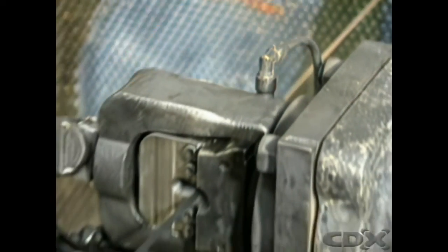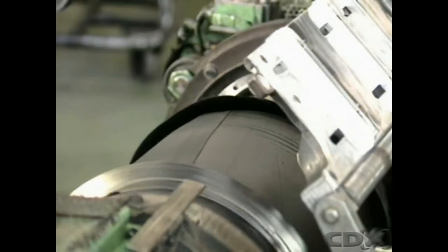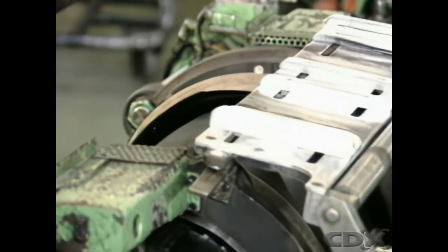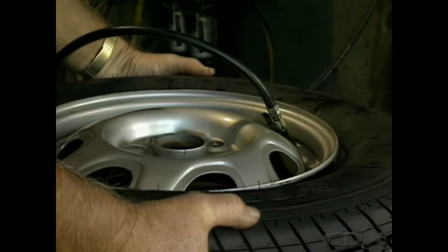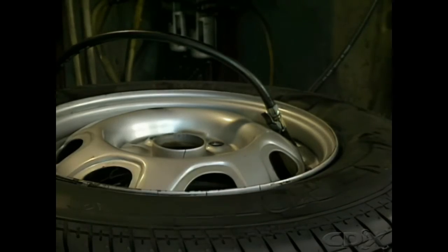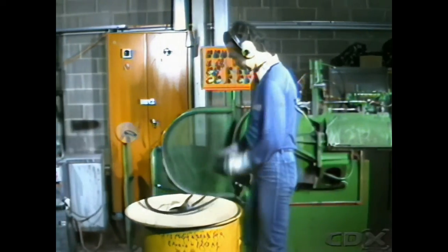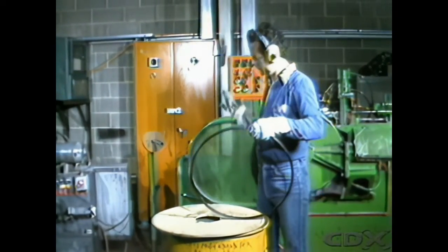The bead of the tire is made of a cord of high tensile steel coated with rubber. The end of the ply is wrapped around the bead, which is then wrapped in rubber to stop chafing of the plies and also to seal the bead against the rim. The length of the wire used for the bead determines the rim diameter of the tire.